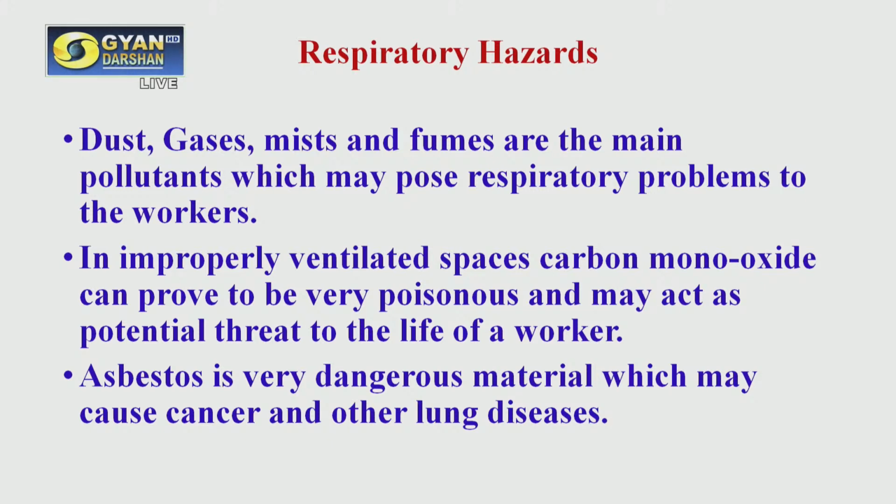So these workers should be told how they can make themselves safe, because these are part and parcel of a construction site. Workers should be trained how to protect themselves from these respiratory hazards. What they can do basically is wear a mask. If there is only a dust problem, then various types of masks are available, and a simple dust mask can be used.